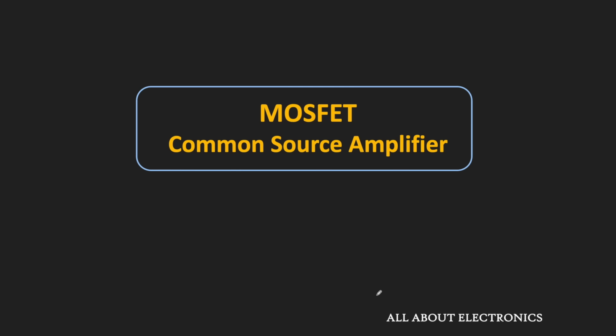So in this video, we will learn how the MOSFET can be used as an amplifier in the common source configuration. And using the small signal analysis, we will also find the expression of the voltage gain, the input impedance, and the output impedance of the amplifier.